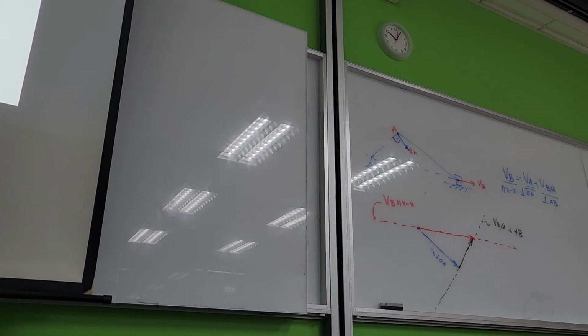And then what is our VBA? Look at the equation. R omega AB times RAB, and from here now we are finding the omega AB, the connecting rod rotational motion. Clear? Remember that? That's how it will be.